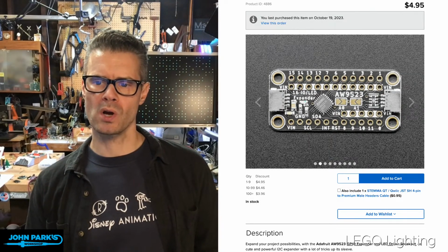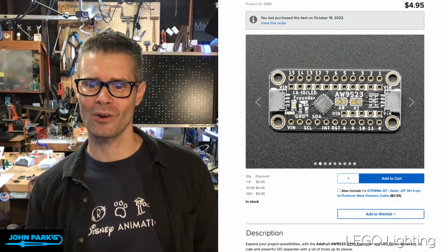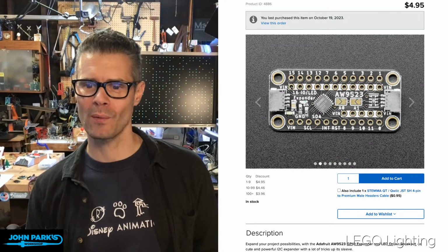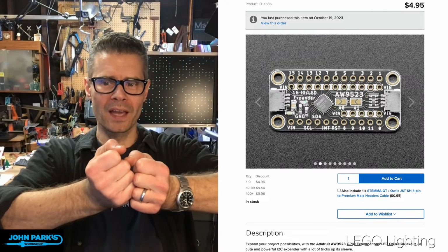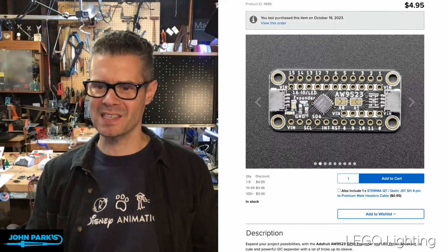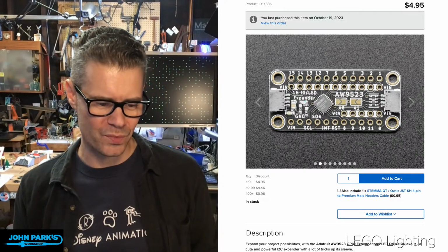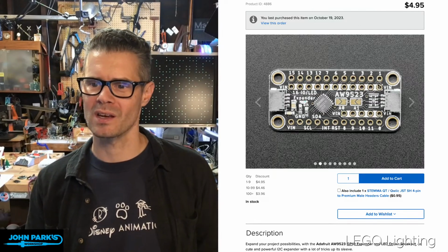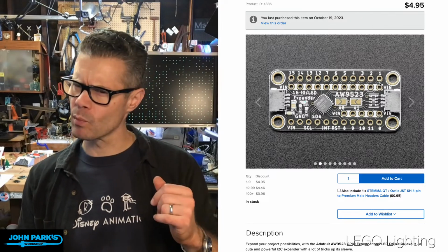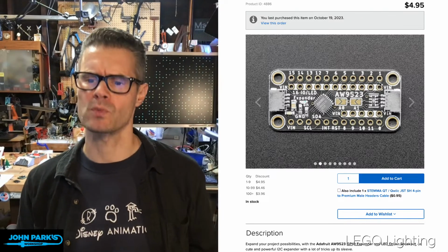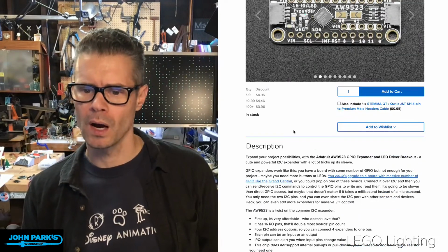So those are all on the same line, but it's really nice that you have them replicated all the way. So thank you, Lady Ada, for doing it that way. It means you're not trying to fit 16 wires into one hole and then the other 16 are spread around. It actually makes this a lot easier to socket and work with. So I really like this board a lot. You can get 2 of them on one I2C bus, I think, or maybe more. There are 2 jumpers for address. So it's probably more than that, maybe 16 of them or something like that.